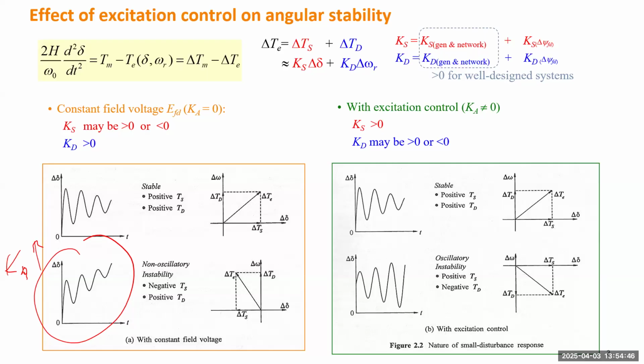But if you see a generator like this one, it means the excitation may be too strong for that generator. If you decrease the Ka, that can switch it to the first condition, right? Therefore, it can switch to this condition. So if you jump between those two conditions, the generator always becomes unstable. Either it is flying away from the rest of the system, or it has growing oscillation, which means you do need the PSS. That's a very important trick for you to make a system stable.